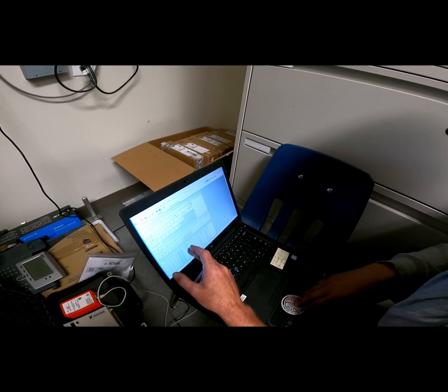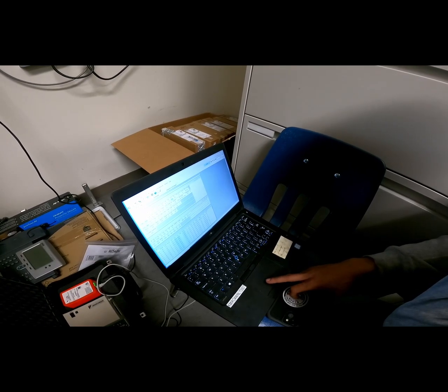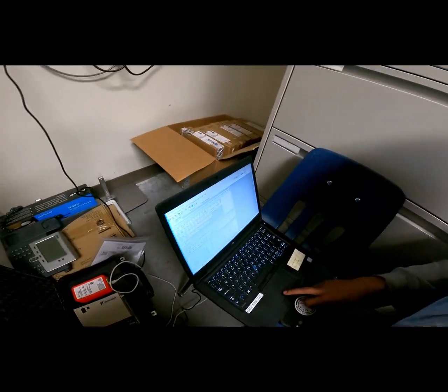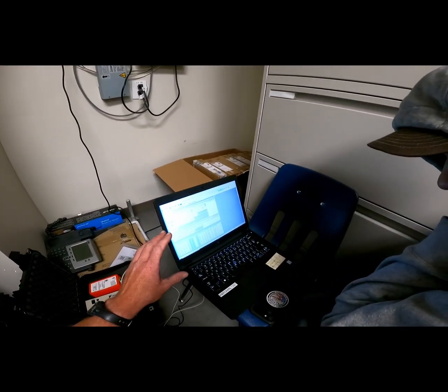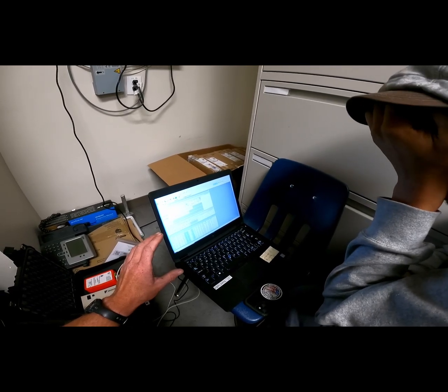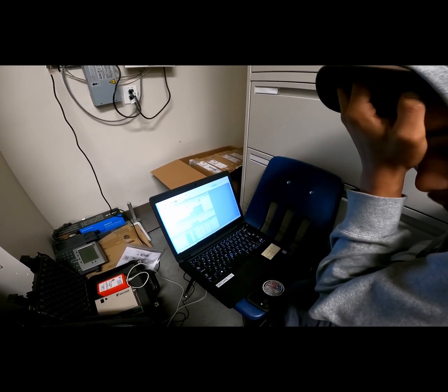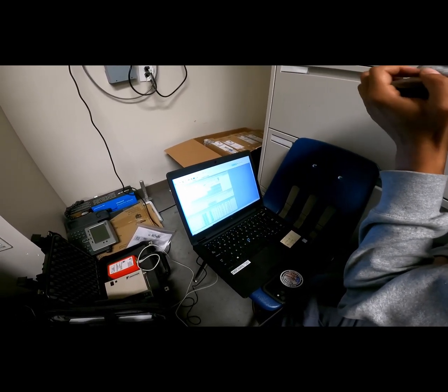So how about our superheat values? Are they all around 0 to 10? Yeah, except for that one. If you see values in the 20s, that would be cause for concern. However, these units take a while to really get going and run the way they're supposed to. Nothing is fast with VRF, so if you see something out of the ordinary, it needs to stay out of the ordinary for a while before you can say that something's going on.